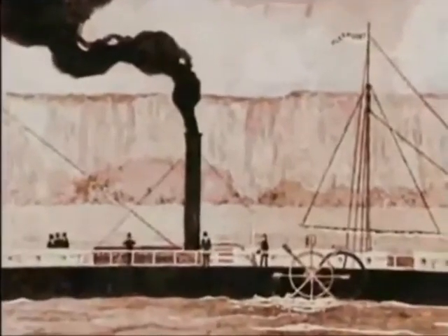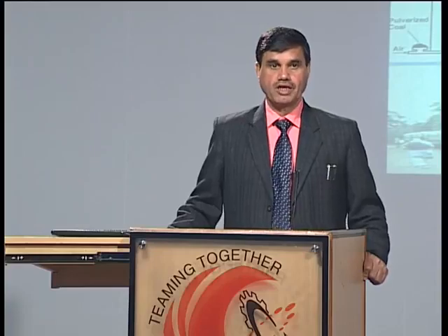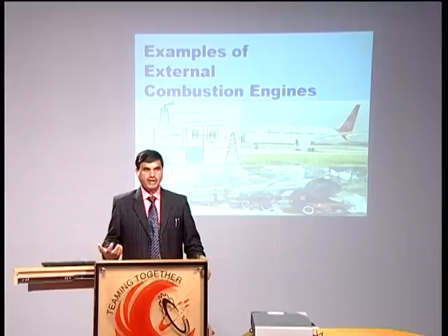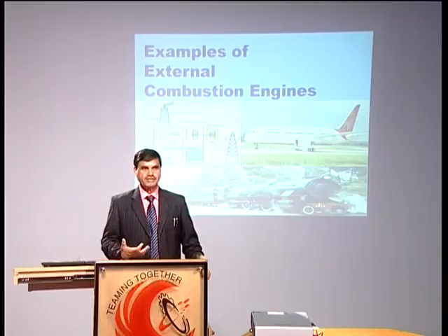So, we have seen both types of engines, internal combustion engines and external combustion engines. The similarity between these two is that both are converting heat into work. The dissimilarity is that internal combustion engines have combustion inside the cylinder, while external combustion engines have combustion outside the cylinder, where steam is generated. In the case of an internal combustion engine, we have observed only one working fluid, whereas in an external combustion engine there are two working fluids, the burnt products and the steam.